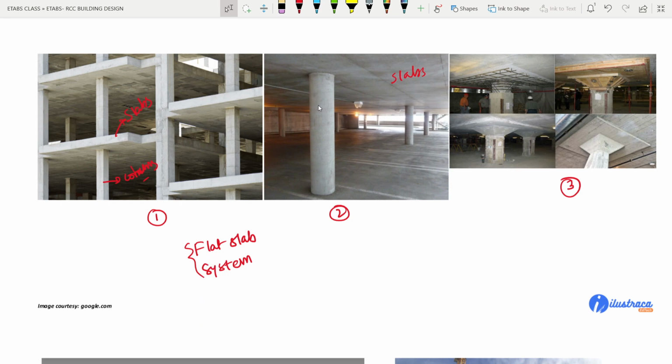Okay, the load will be transferred directly from slab to the columns. There is no other way of transferring the load actually. And this kind of structures are not recommended in seismic zones. Even this kind of structures are not recommended everywhere. You can see when you are constructing this kind of slabs, which are called flat slabs, you may have a higher span in between the two columns.